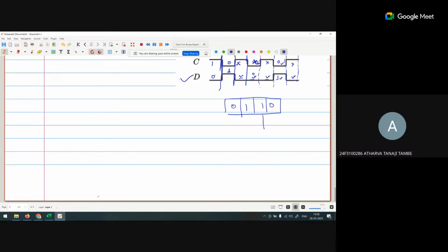There is a shift register with bits Q0 to Q3 having value 1101, and the XOR gate is applied to Q0 and Q3, and we have to make it 1111, all ones.